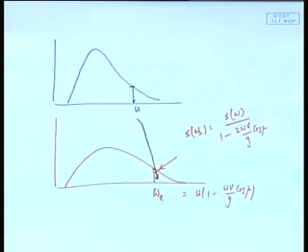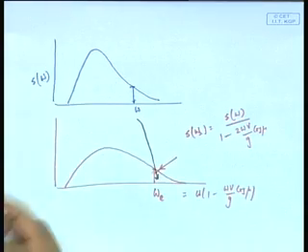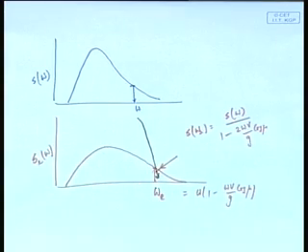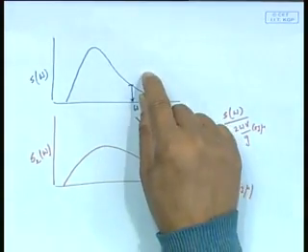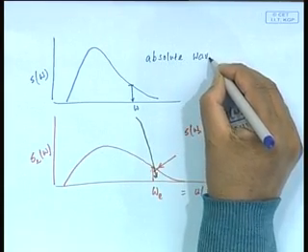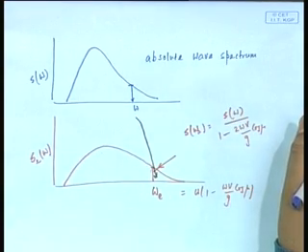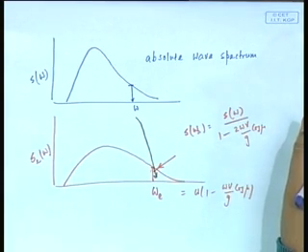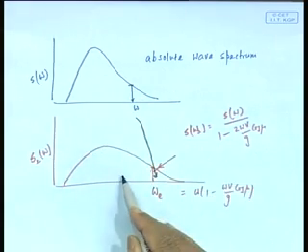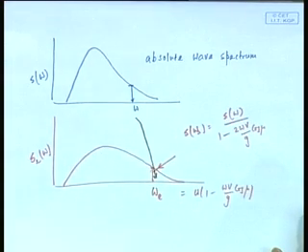So, what has happened now, you see, that means for each point I can get this. That is very simple, right, as far as calculation is concerned, S omega, and I am calling it S E omega. Okay. So, what we call this, we can call absolute. This is the one that I got from the formula, this is the one that has been actually obtained at a stationary point, which is what the observers gave. This is the same wave, same spectrum as viewed on board the ship. Obviously, this cannot have a simple formula because it depends on V, it depends on mu, on what angle to the waves and what speed you are moving.